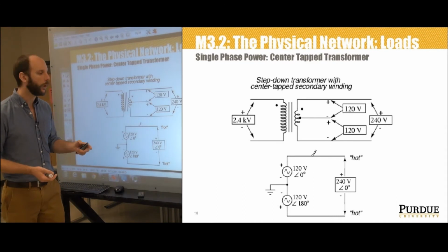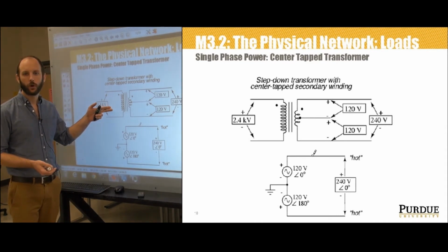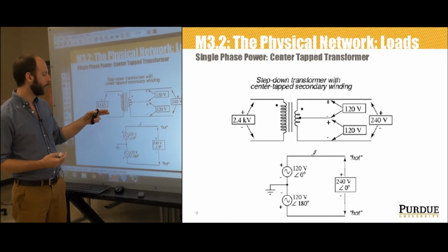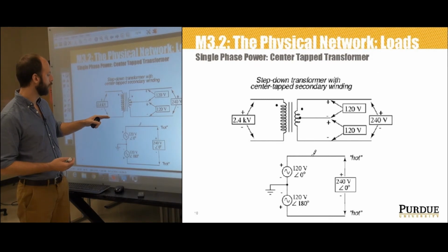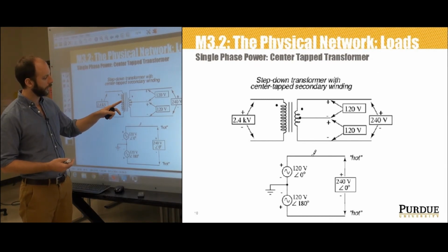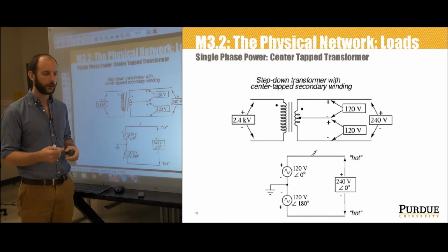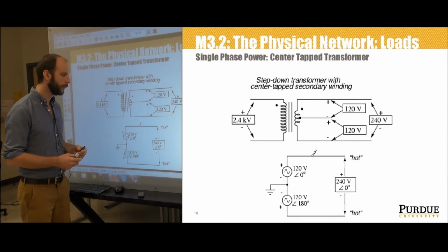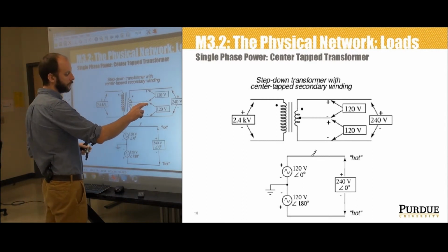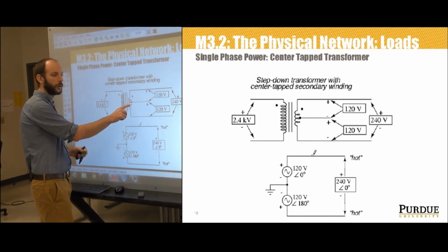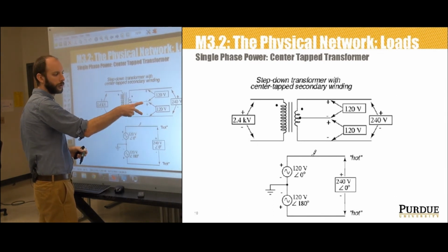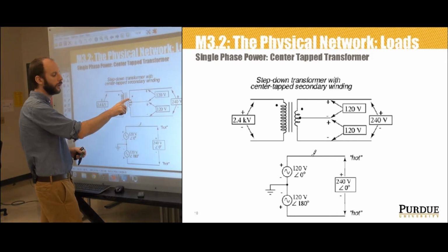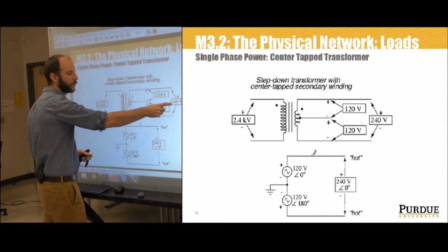And what we can see is that connecting across the 2 live wires is going to supply 240 volts. How this is achieved in the US is through the use of what's called a center tapped utility transformer. In this diagram, we see that we've got an input voltage at 2.4 kV. We've got a transformer. Unlike the transformer diagrams that you may already be familiar with, this one has 3 connections, that middle connection being called the center tap. And what we can see is that by center tapping the transformer, which basically is just dividing this coil in half, I've created 2 120 volt circuits. If I ignore the center tap and connect across the output terminals of the step-down coil, I get 240 volts.